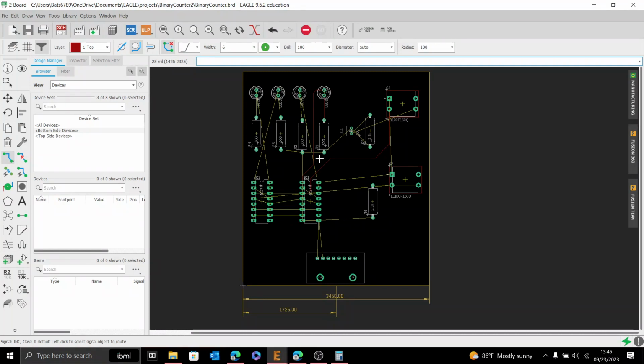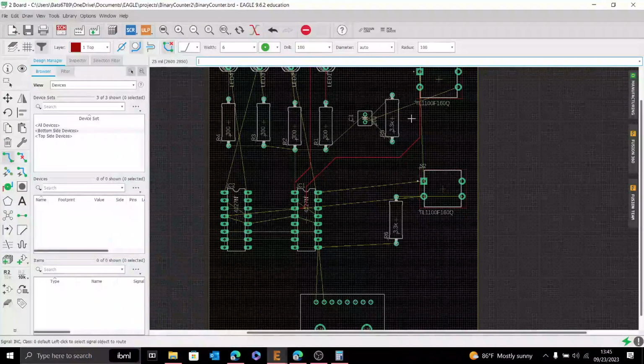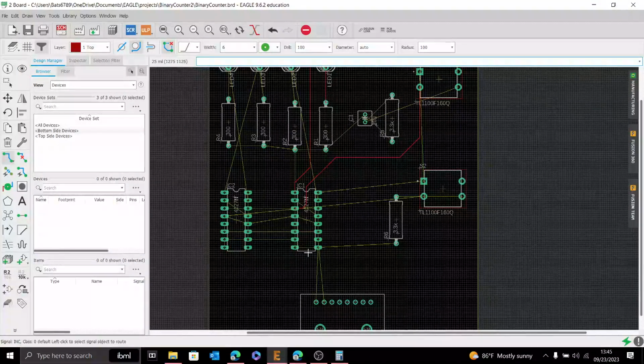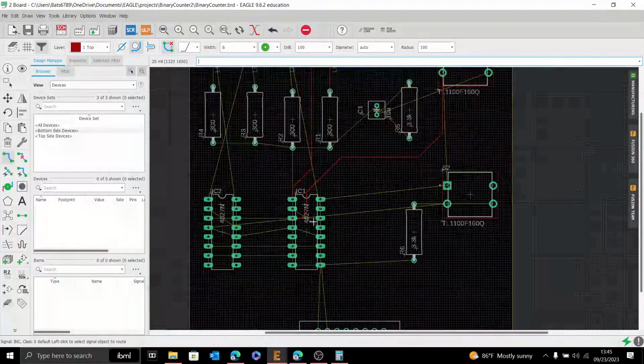Just for aesthetics, there is also some signal reasons as to why you might want to do that, but we don't have anything signal sensitive here when transitioning to a via. And so these are just kind of design habits I picked up. Avoid swapping layers as much as possible. And so under it just looked like a nice way I could keep these close together and get to this one, which would have been a pain to get to later. I could have gone way out here and made the trace longer and block up all these pins to where they now all have to go to the bottom layer to get to their next route. I think this just works the best in my opinion. Are there any questions related to that?